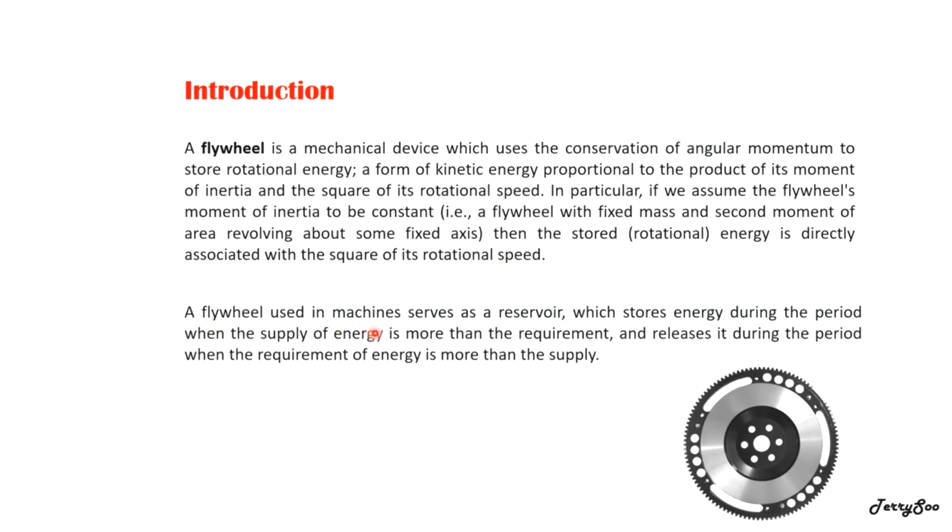So a flywheel used in machines serves as a reservoir, which stores energy during the period when the supply of energy is more than the requirement. Especially when you refer to a four-stroke internal combustion engine, during the power stroke there will be excess energy.